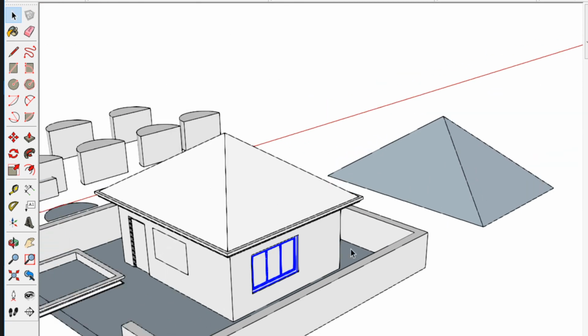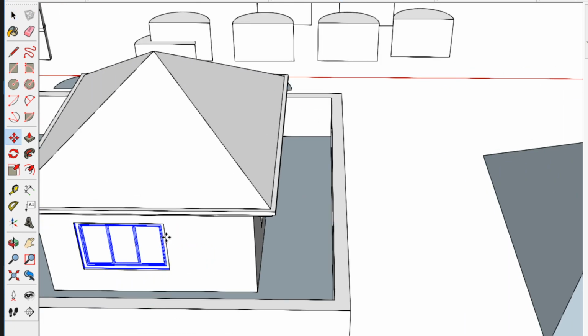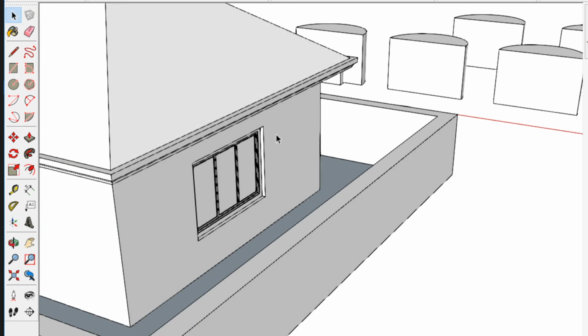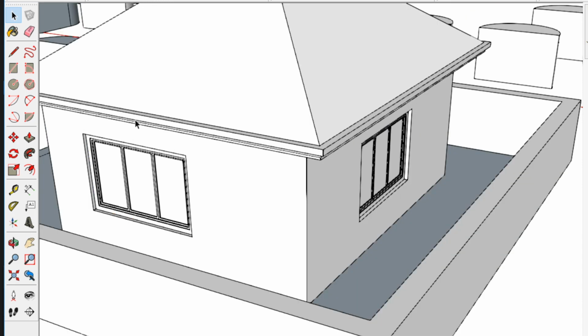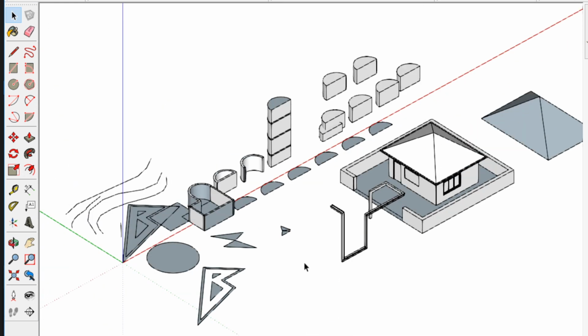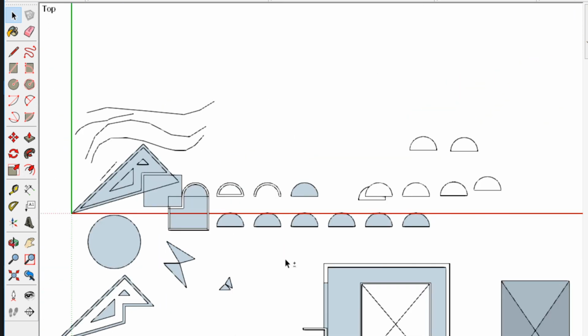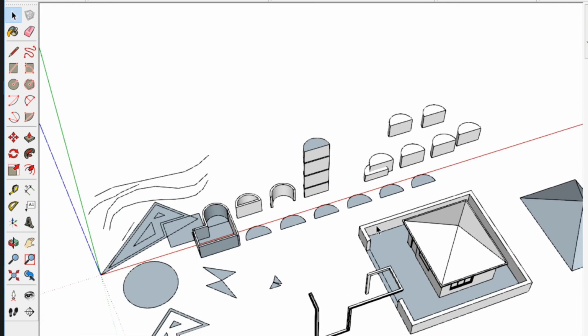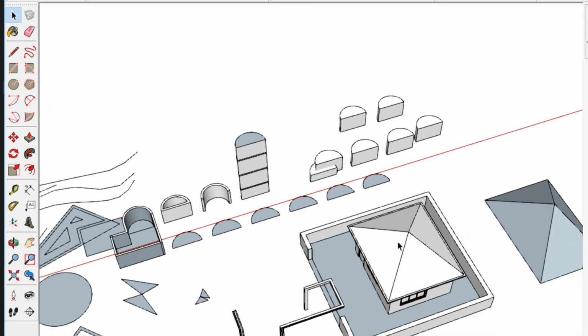If you know that you're gonna use something over and over again, or just twice, better have it in a component. Because if this was a group and you want to put this here and you want to edit this, then you'll have to copy this and put it there all over again, or redraw that. Okay, maybe that's a simple 3D modeling for now. I actually have a script, but I just went impromptu because it was so hard to edit stuff, and I had the wrong colors as well.